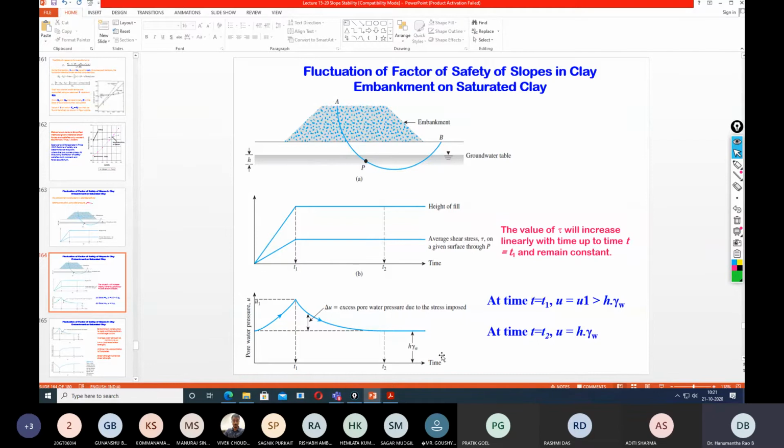Therefore, the initial pore pressure can be designated as gamma W into H. Since it is fully saturated, we have an assumption from the triaxial testing, and an assumption from the consolidation, that when any soil sample is fully saturated, the entire load is initially taken by only the water component,